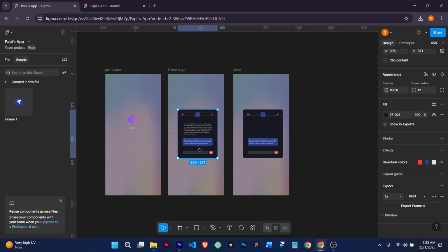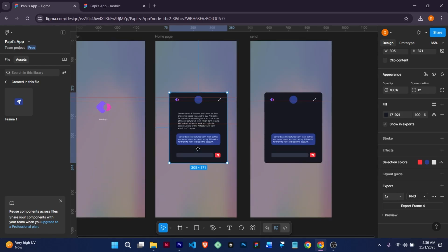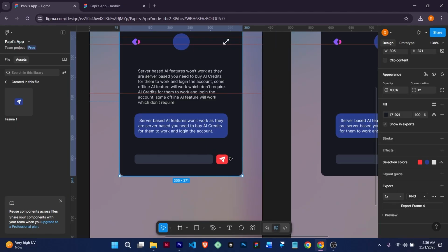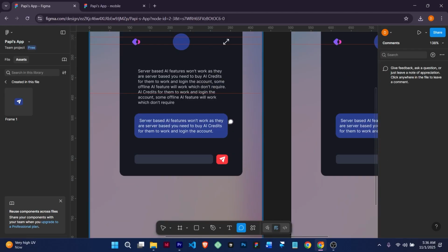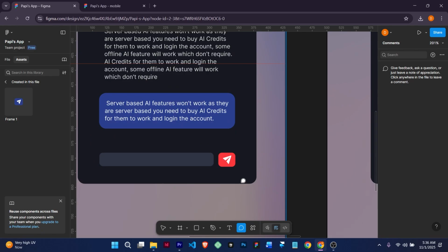So let's say you are working with a team and you are done designing. One good thing about Figma is the teamwork. You can design and share for others to edit everything. We also have commenting. As when you're writing code, you can comment. When you're designing with Figma, you can also leave a comment. With this icon, which means comment, or C for shortcut, you can comment on any side of your design. Let's make an example. We are going to comment on this button, so you click on it and you add a comment.